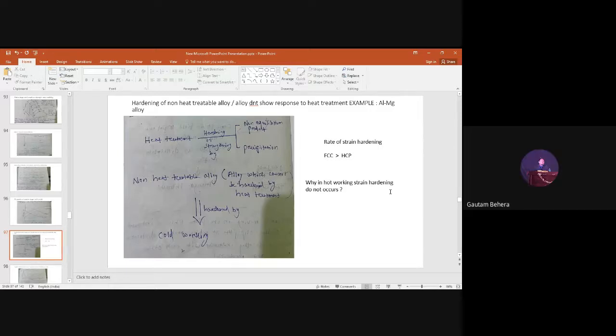Okay, Panda, can you repeat what you told about HCP or FCC? Hexagonal has 3. Yes, very good. So HCP metals basically have 3 slip systems and FCC has 12 slip systems. So if the slip systems are more, what will happen? Which one will be more ductile? More slip systems, FCC.